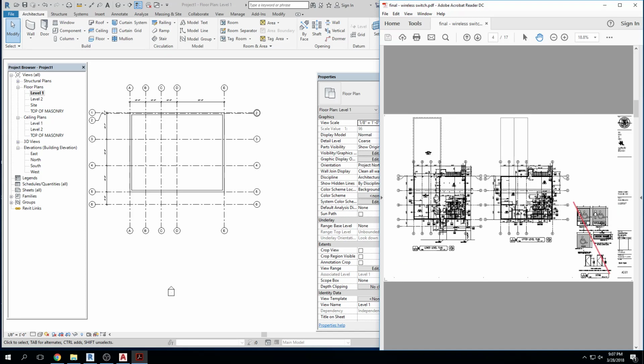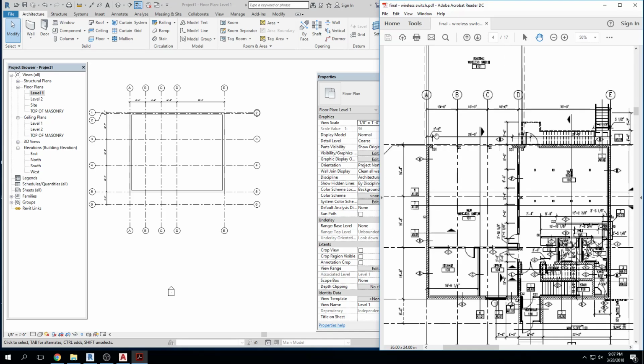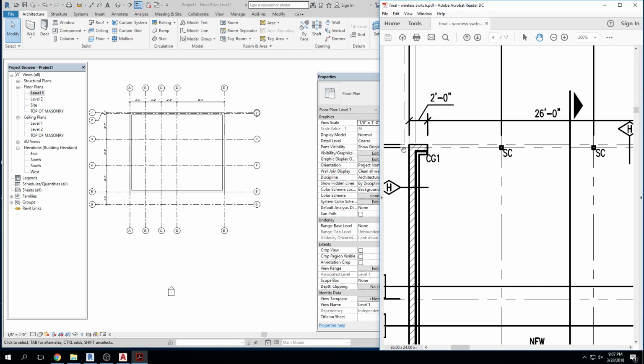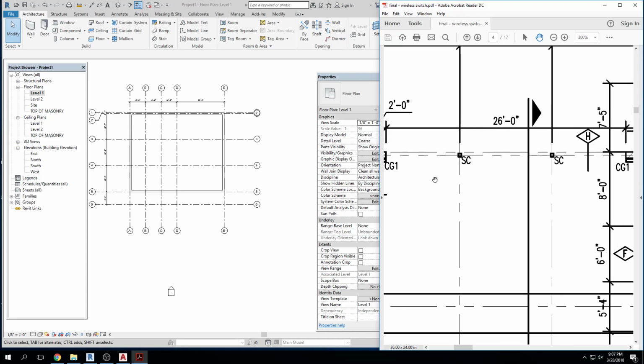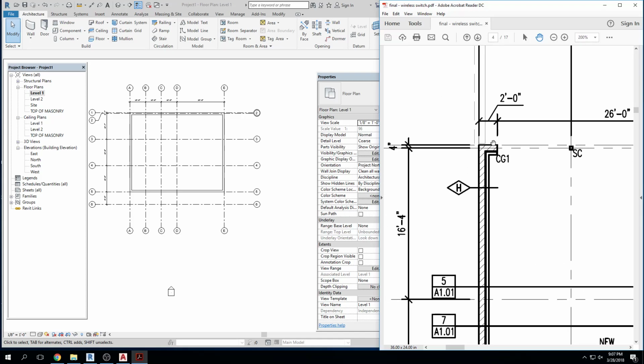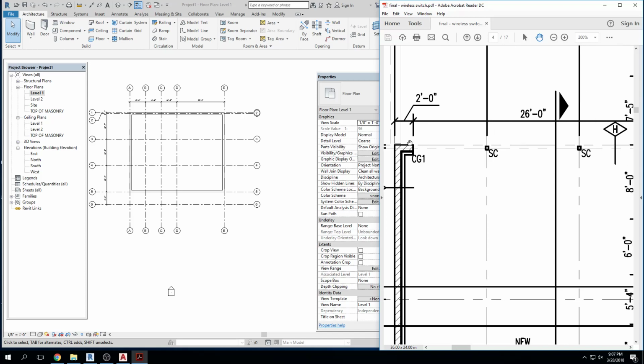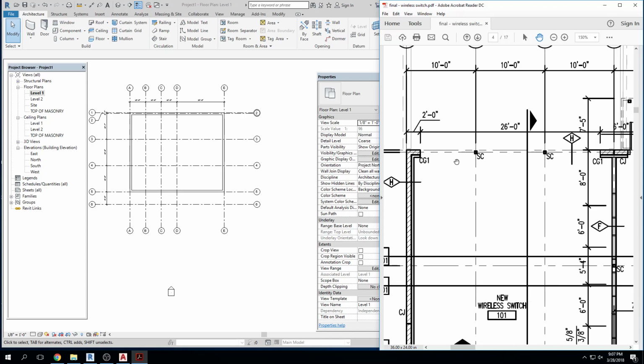I mean, that makes sense for locating things, saying, hey, around C2. But they have a line of structure right there. There's an opening that was right there. And so they want to hit the exterior face of wall where the block is going to go. And then they want to hit that line of structure that's going to hold open that big opening right there, where there's probably going to be a lintel above holding it open. Oh, yeah. Okay.